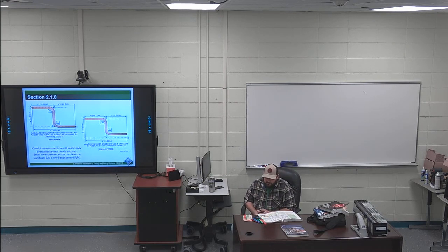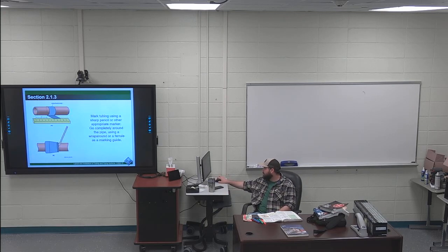Second to last paragraph on the page, on the right hand side of page 23, first 2 sentences are highlighted. When measuring with a measuring tape, do not use the end of the tape as a starting point. The end of the measuring tape gets damaged over time and can lead to measurement inaccuracies. They usually call that pulling an inch. If you look at this picture, they pulled an inch. So they're not starting at 0, they're starting at 1, and say this pipe goes all the way to 12. This pipe's not 12 inches long, this pipe is 11 inches long. Or they're measuring to 5, this is 4 inches between 1 and 5, if you're marking your stuff right there. Pulling an inch just makes for a more accurate measurement.